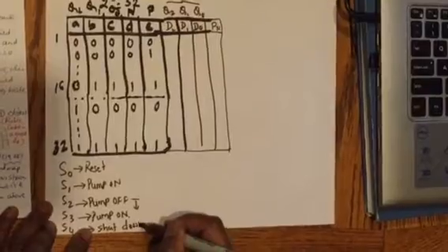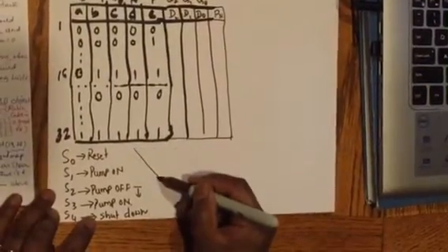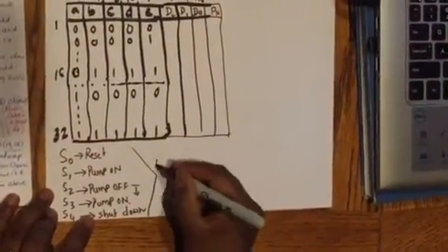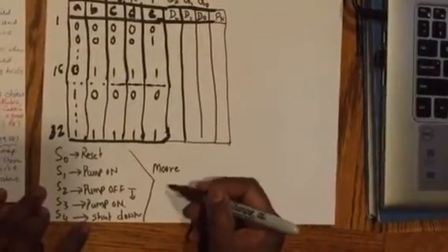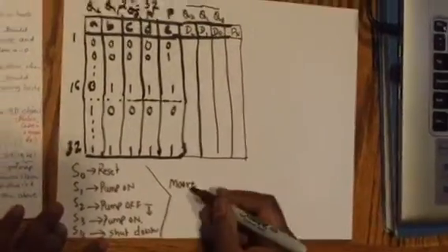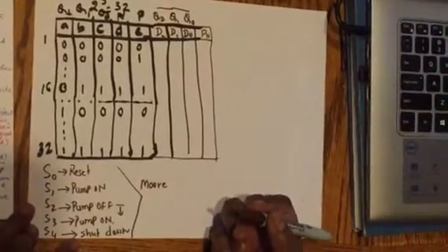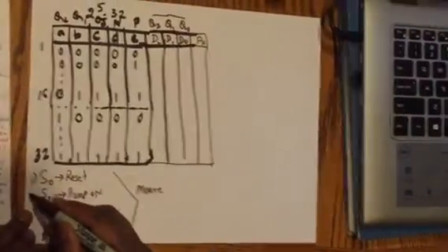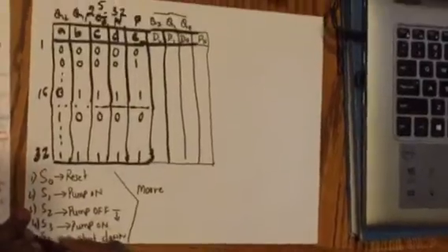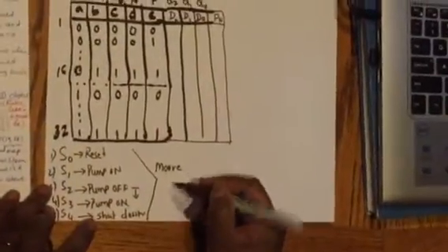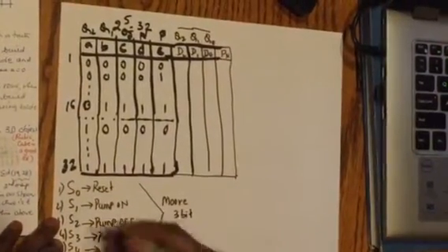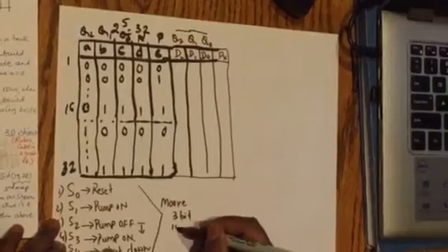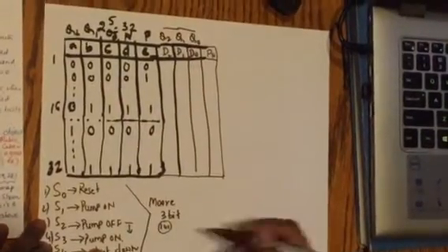So, if these are the number of states for a Moore design, how many digits do you need in order to represent a number that is decimal 5, which is 1, 2, 3, 4, 5 states in total? Basically, it needs 3 bits because 5 can be represented as 101, which is a 3-bit minimum.